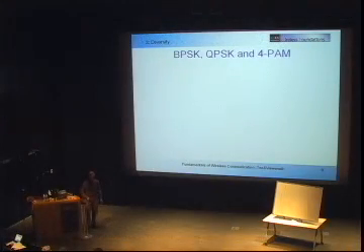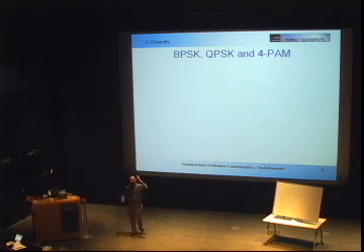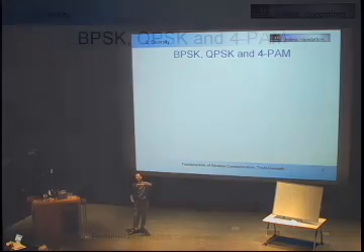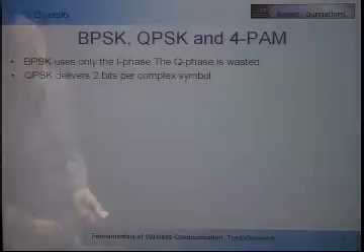I've used BPSK. Okay? From the communication system point of view, what does BPSK mean? BPSK means I'm sending a real symbol, right? Plus or minus A. So that means I'm not using the Q phase, right? I'm only using the I phase. So remember, in my communication system, I have 2 inputs, right? Because I'm inputting a complex number. There's real and there's imaginary. So BPSK means I'm only using one of them and I'm not using the other one. That's stupid, right? I should use the other one. And that's why people use QPSK.